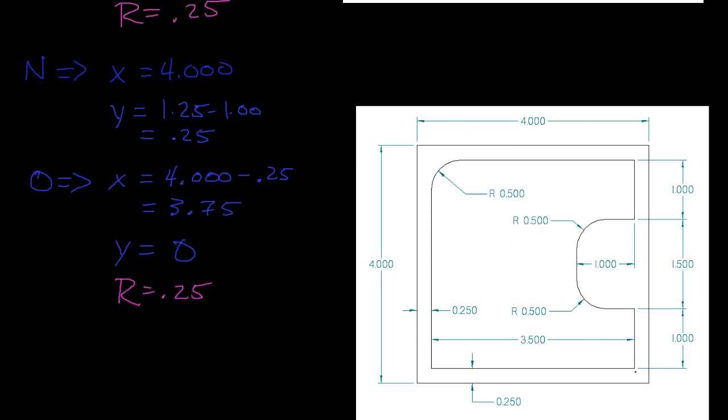All right, so I'm right here with my cutter at point O, and now I need to go to point P, which is off of the material. I'm going to come along here and come to there. So this is at x equal to negative 1.00. All right, so this is point P, the final point in the tool path here.